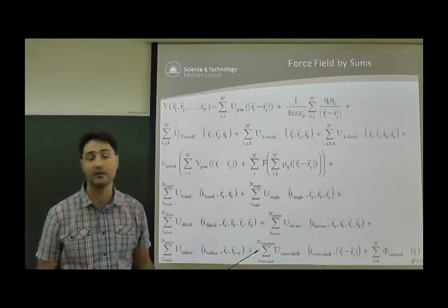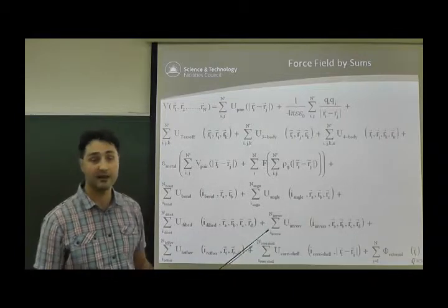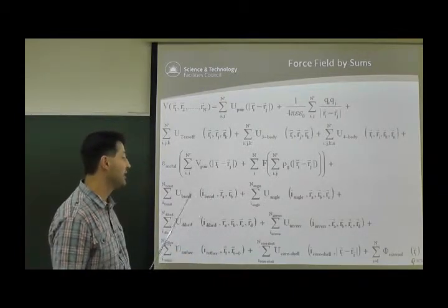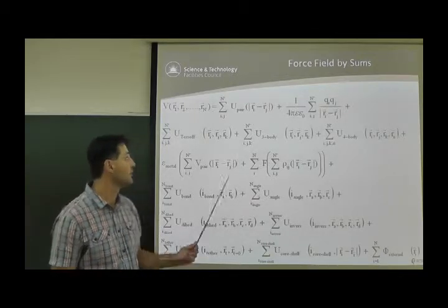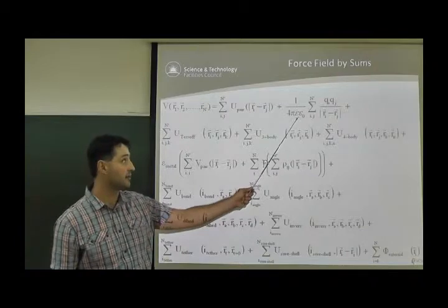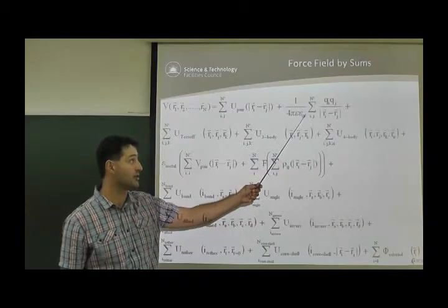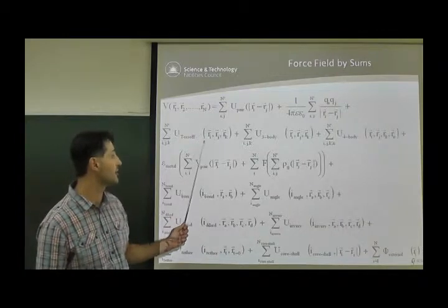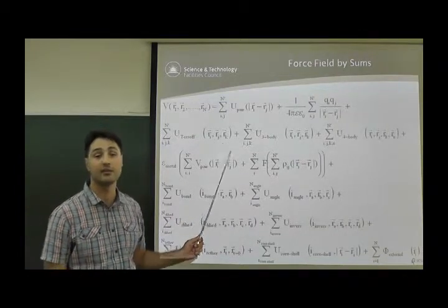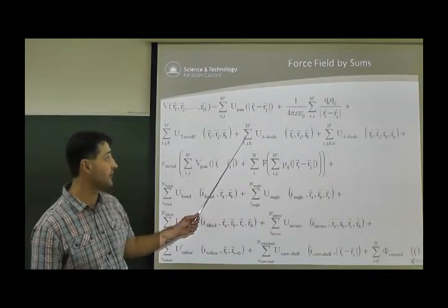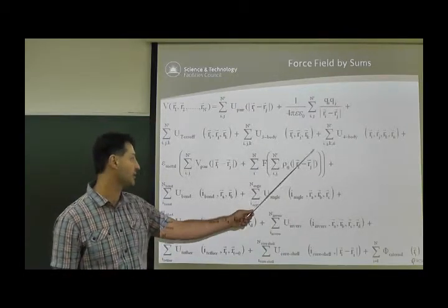These are defined by type of particle, and the rest, with the exclusion of the external force field, are defined by site. So what we have, as I mentioned, we have pair. This is again pair but long range, the Coulombic interaction. Tersoff is a mixture of 2- and 3-body interactions. In other packages, there are Stillinger-Weber interactions, which are again a similar mixture. We have pure 3-body, pure 4-body interactions.